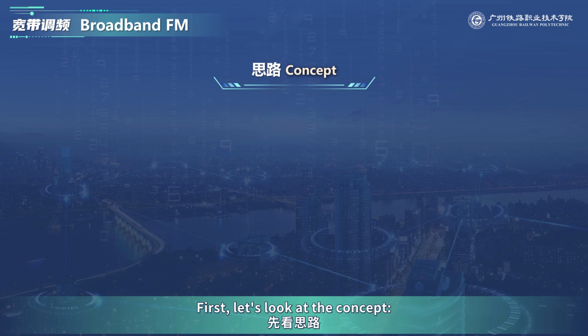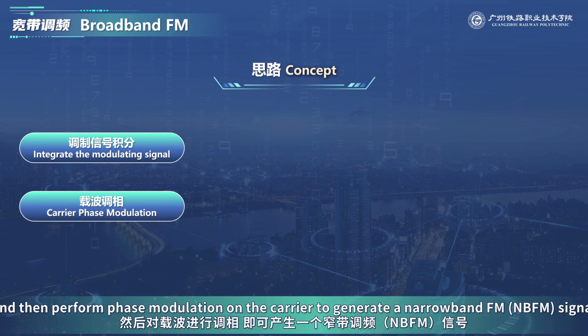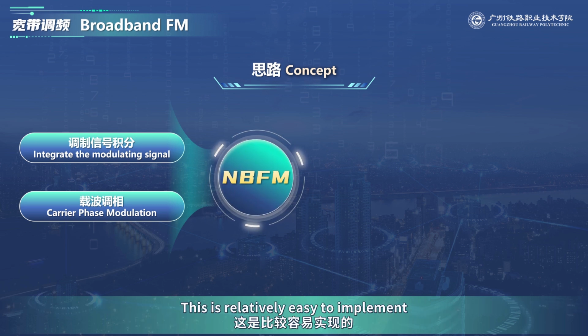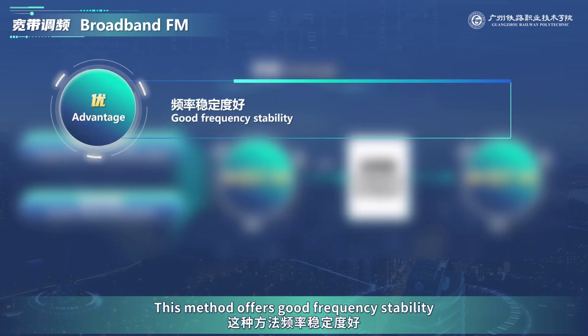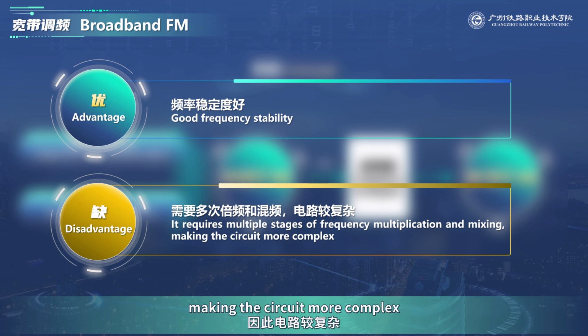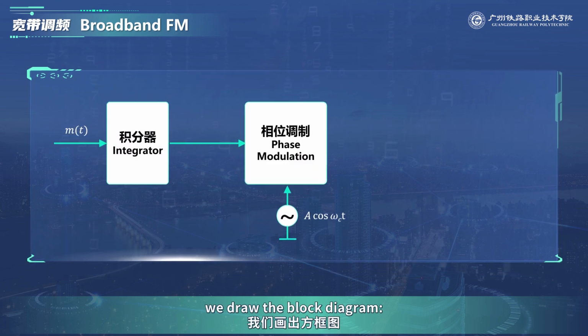First, let's look at the concept. First, integrate the modulating signal, and then perform phase modulation on the carrier to generate a narrowband FM (NBFM) signal. This is relatively easy to implement. Then, pass it through an N times frequency multiplier to obtain wideband FM, WFM. This method offers good frequency stability. The drawback is that it requires multiple stages of frequency multiplication and mixing, making the circuit more complex. Based on the above concept, we draw the block diagram.